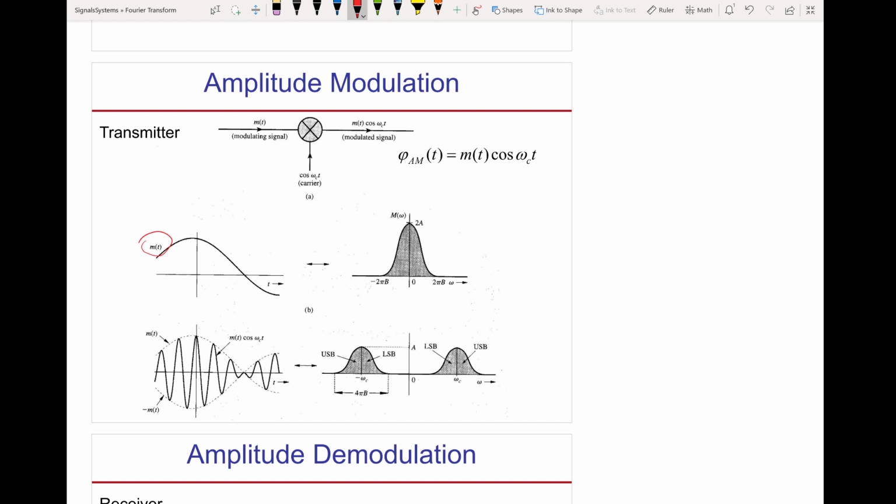There is no way we can transmit this in radio frequency or wireless. At 20,000 hertz, the wavelength is lambda equal c over the frequency, where c is the speed of light, 3 times 10 to the power of 8, and the highest frequency in speech is 20,000 hertz. So the wavelength is 1.5 times 10 to the power of 4 meters. You need an antenna at least half the wavelength. That's 15 kilometers, so you need an antenna 7.5 kilometers long, which is impossible to build.